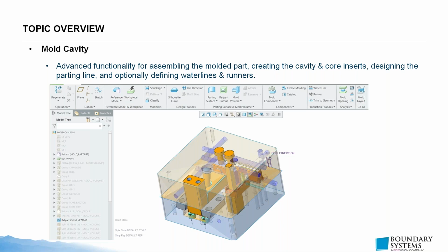There is a cavity insert set, as you see here on the screen, that is duplicated and arrayed, if you will, inside of mold layout to produce a two-cavity tool. But in order to optimize the designer's time, there's no need to design the duplication of these things. We simply create the single insert set, as you see here, representing a single cavitation inside of mold cavity functionality, and we duplicate and cavitate, if you will, those insert sets inside of mold layout.